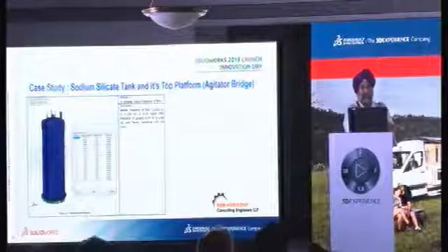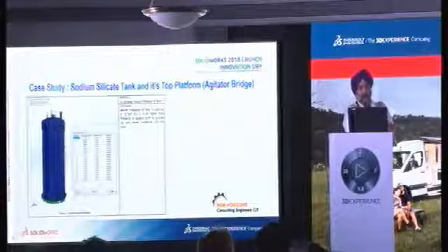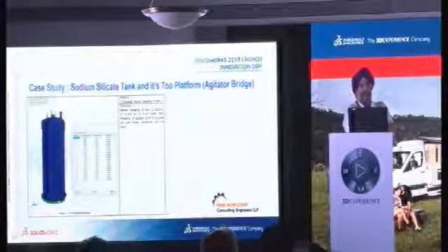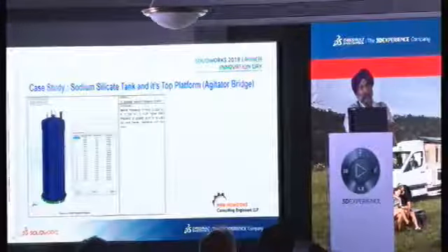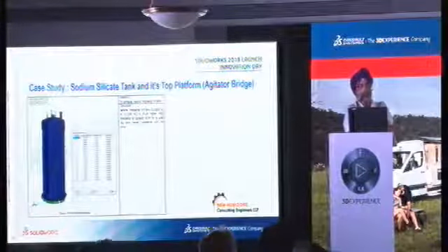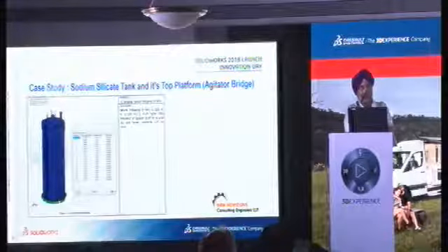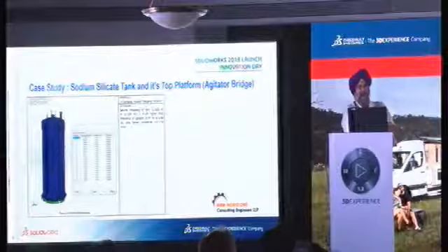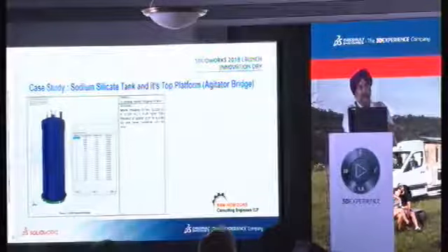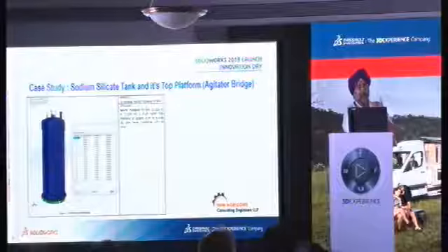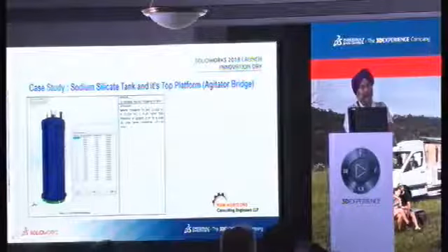the customer was very worried that resonance should not occur. The first task was the natural frequency of the baffles. So here we took help of SolidWorks simulation, the supports or the number of supports, to ensure that there is enough gap or enough margin between the induced frequency and the frequency of the baffles.